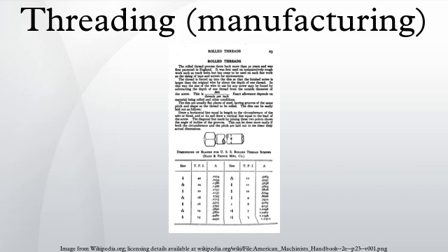The 2-die cylindrical process is used to produce threads up to 6 in diameter and 20 in length. There are 2 types of 3-die processes. The first has the 3 dies move radially out from the center to let the blank enter the dies and then closes and rotates to roll the threads. This type of process is commonly employed on turret lathes and screw machines. The second type takes the form of a self-opening die head.